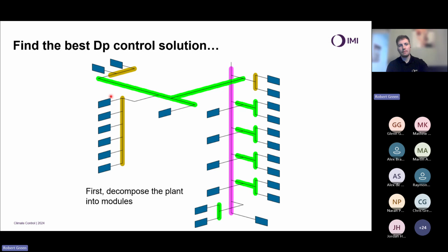And the thing we need to bear in mind and be aware of with DPCVs is we must ensure, if we are providing dynamic balancing, differential pressure control solutions into a building, into a project, every single part of that system must be protected. If you say, well, do you know what? I only care, this unit is the one I really care about being correct. So I'm going to put a DPCV on there because we can't have any variations in differential pressure and flow on that unit because it's imperative that it always operates.